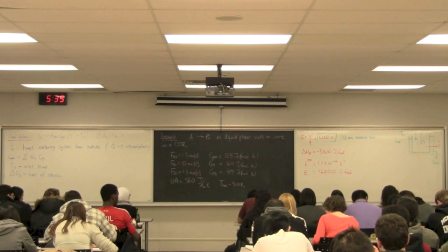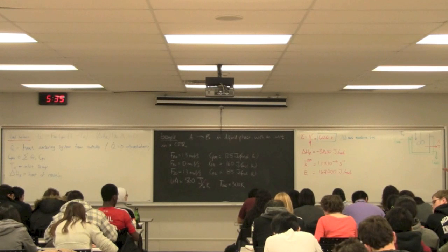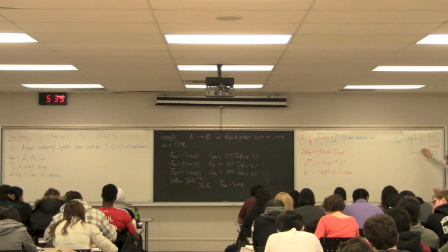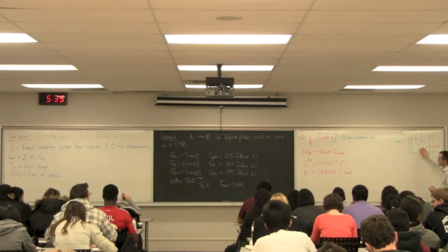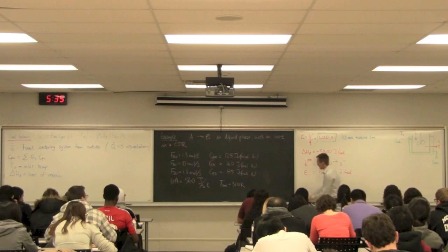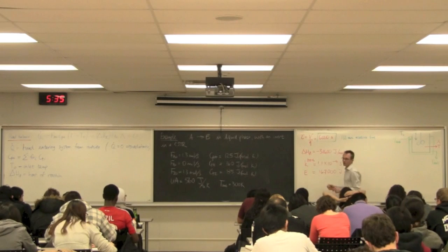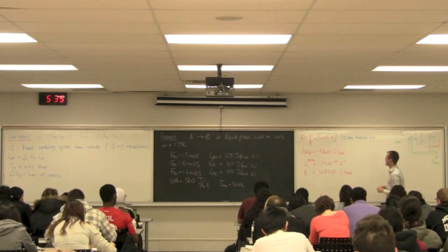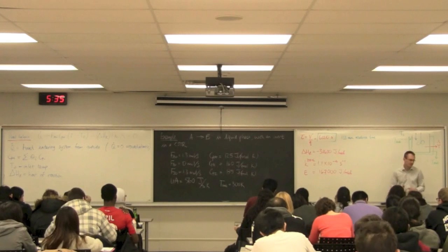So that's where we were last night. We know that as my system operating point changes, this temperature changes in this CSTR. If I move to a steady state at a certain temperature, my rate constant K is also going to change. I've been given my rate constant K at 350 Kelvin, and also the activation energy, so I can recalculate the rate constant at any other temperature.